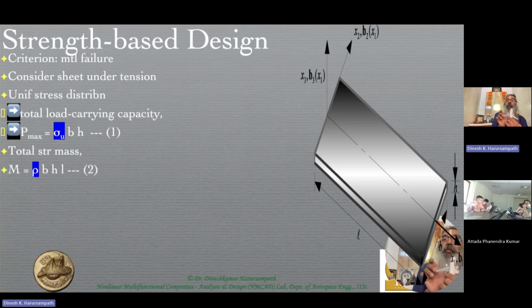And it's quite clear that we as structural engineers don't have a play around with that. The aerodynamicist will dictate it based on the planform area and the aspect ratio chosen for the appropriate aerodynamics, based on requirements like payload, the cruising speed, the cruising altitude, and the range. From these requirements you determine the overall sizing of the wing, and therefore L is something that you and I, as structural engineers, cannot play around with.